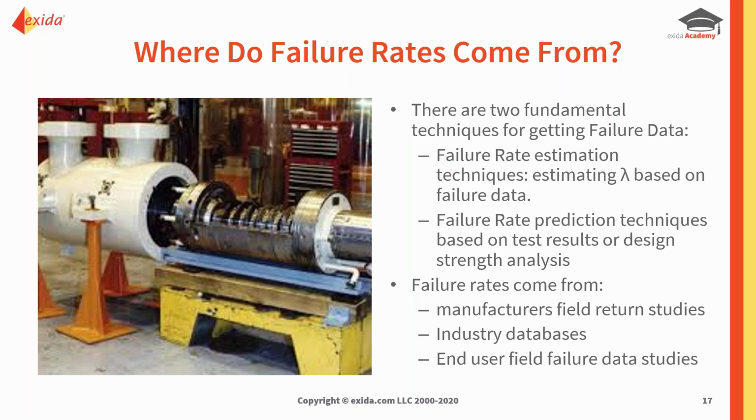Industry databases, that's another good source of information, and there's quite a lot of data out there now. OREDA, for example, which is the Offshore Reliability Equipment Database, which is operated by DNV, and the data is reviewed by SINTEF, is based on information from North Sea oil platforms. There's also, Dow has a lot of data. There's a pipeline company that publishes data. And of course now the CCPS, the Center for Chemical Process Safety, has the PERD, which is the Process Equipment Reliability Database, where they are now developing software and taxonomies to be able to gather field failure data.